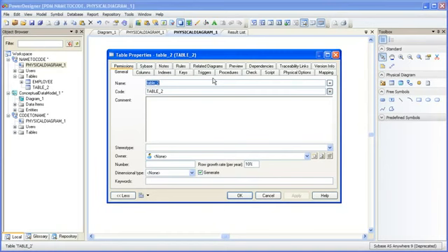Here we have a property sheet that defines a table. And let me call your attention to the equals button on the right side of both the name and code fields. Currently the code button is enabled. This links the name field with the code field. Anything I type in the name field will be reproduced in the code field.